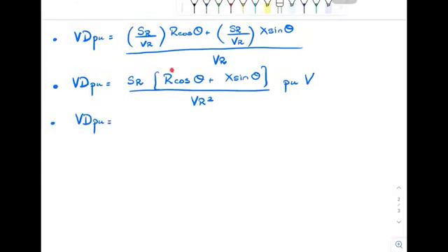now I can write this R in terms of resistance per unit length, and instead of using the total length of the feeder, we can use the effective length, as the effective length will depict the nature of load density as well, which we are going to discuss shortly.